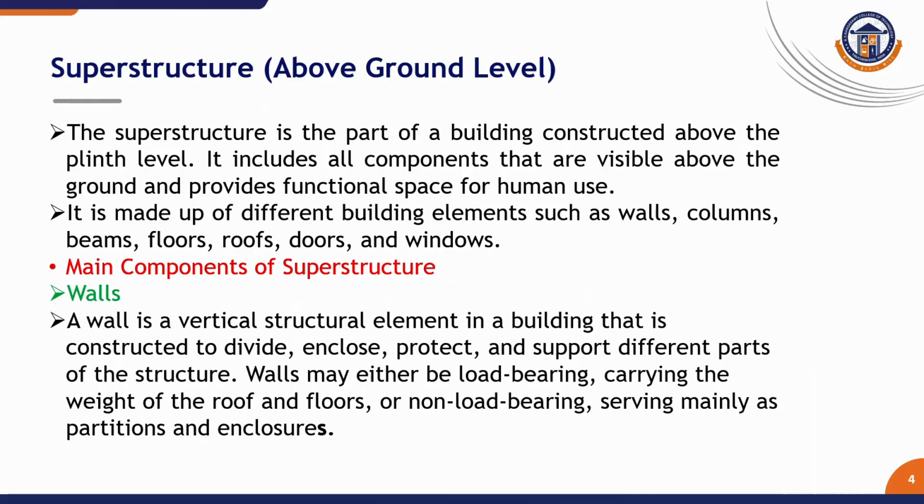A wall is a vertical structure element in a building that is constructed to divide, enclose, protect, and support different parts of the structures. The main component of building is superstructure. Walls may either be load carrying, carrying the weight of the roof and floors, or non-load bearing, serving mainly as partitions and enclosures.